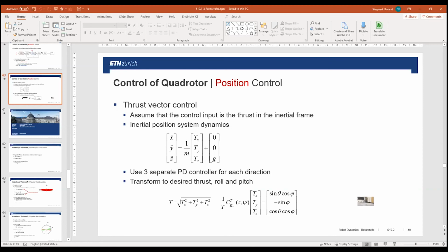But then, if you want to really control it, you have to have a really different control. It's really a different model because you're losing one rotor. But in general, you can still calculate the up force, and this is what is done in the example or the exam, so that at exactly this moment where you lose the propeller, you know the forces and torques acting on the system.